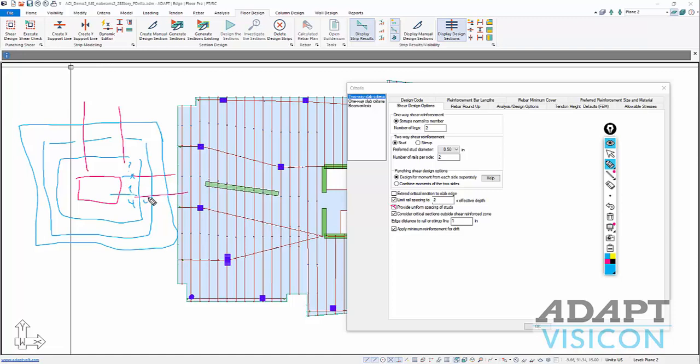This might be L2, L3, and so you might get variances in the number of studs and the spacing between layers, just depending on rounding and the program's mechanism for designing the studs within each layer. And that might lead into a design where you need maybe studs spaced at 2 inches and then 2.25 and then 2.25 and then maybe 2 again depending on rounding. So this is a very specific outcome of the reinforcement.